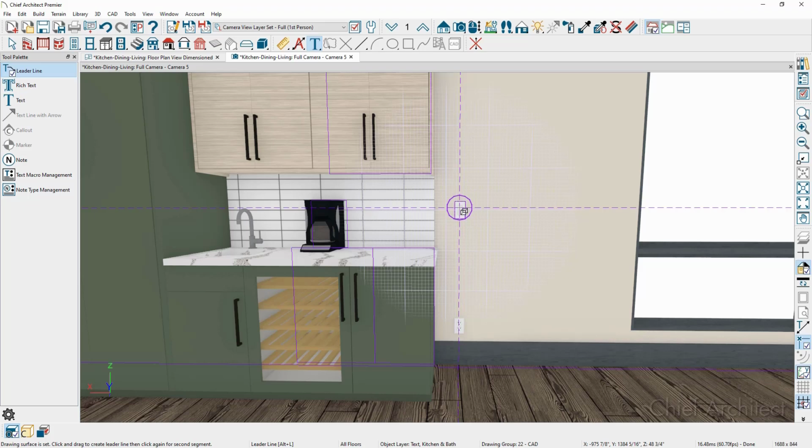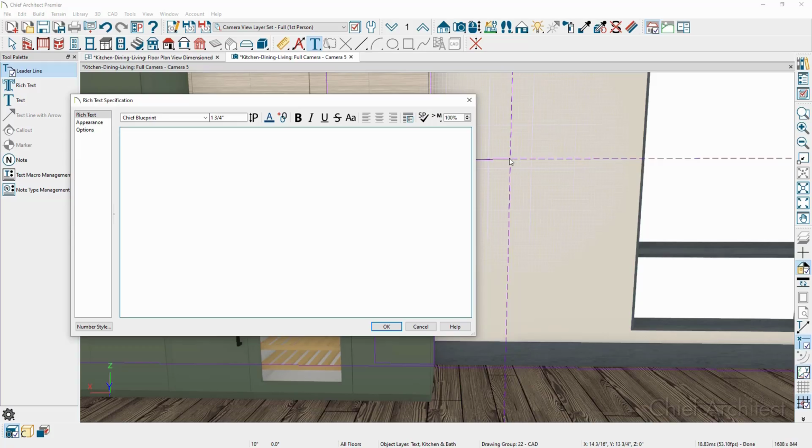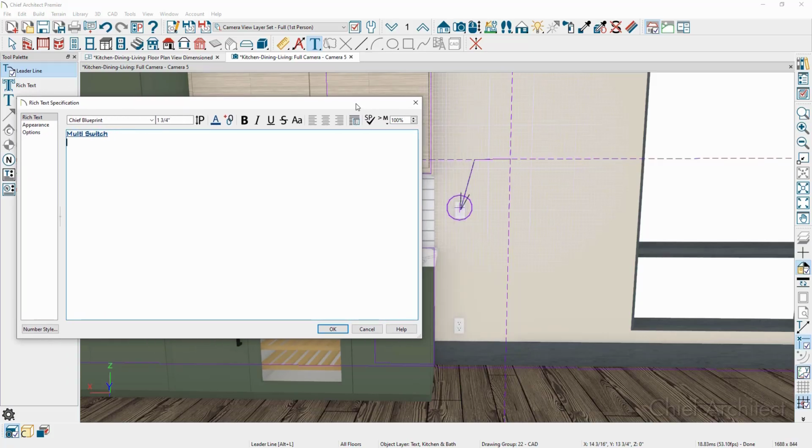and I'm going to left click once to establish the plane. I've established the plane and I get the feedback grid, and then I can come over to the switch and snap to the center of it and right click and draw out a line that will be the arrow segment. Release the mouse and continue the line that will be the second segment, and right click again to place it. I can then add my text, and then because I had snapped directly onto the switch, I can insert a macro with information about it.